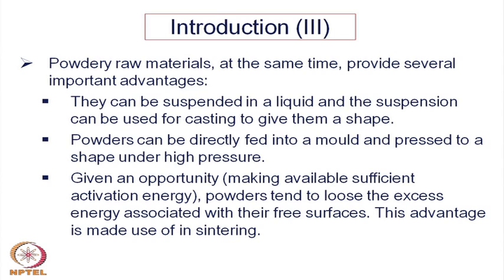In sintering, one provides activation energy by heating to high temperature, so that the excess free energy because of the high surface area can be removed, and the particles can bond together and a strong bond can be developed. We will discuss that, and that is one of the basic steps or basic phenomena of sintering.